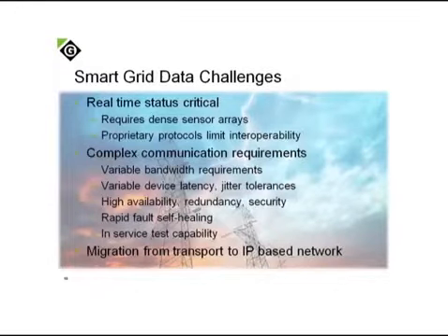That's normal. But with the Ethernet and IP push now with sensors as we move forward, I think we'll see that more and more of these sensor arrays will become Ethernet standardized, and actually that Ethernet IP will be pushed all the way out into the substation, right up into the synchrophasors and PMUs and IEDs that will talk native Ethernet, and so we won't have the interoperability challenge anymore.